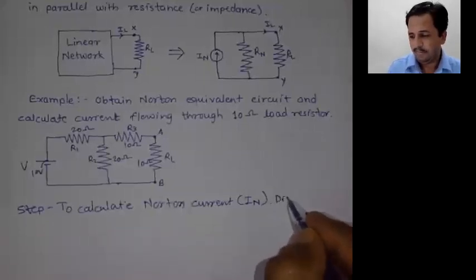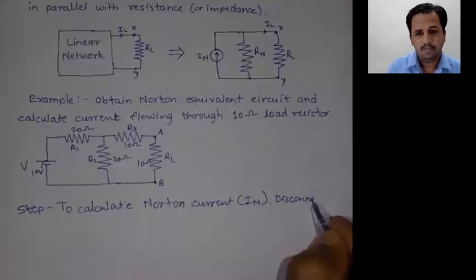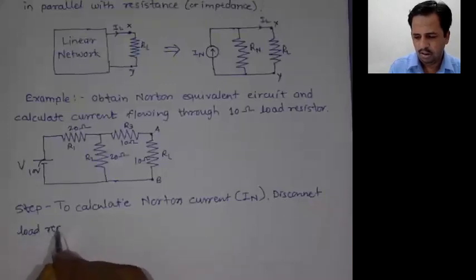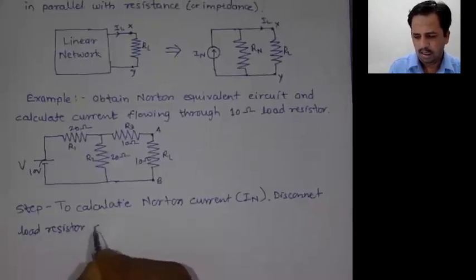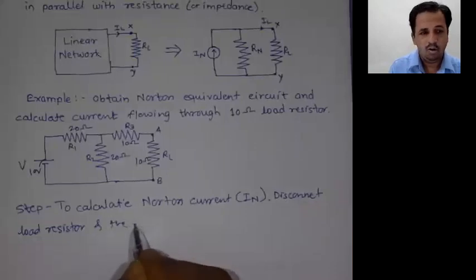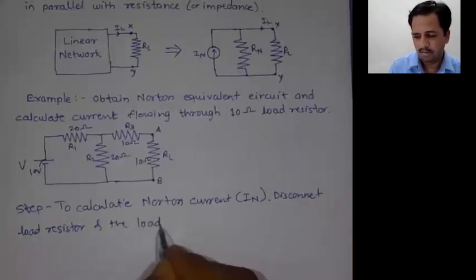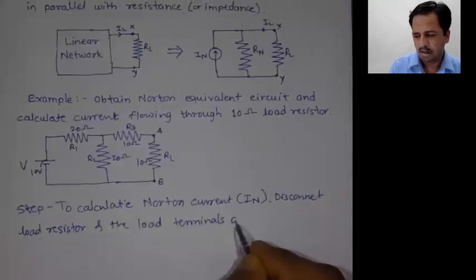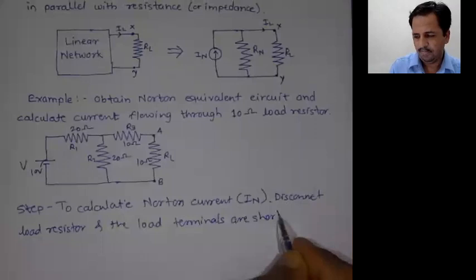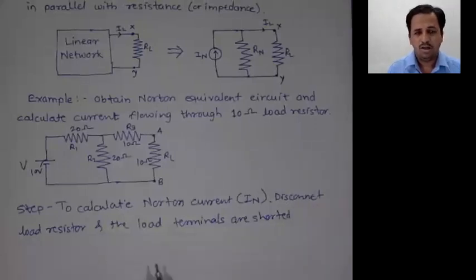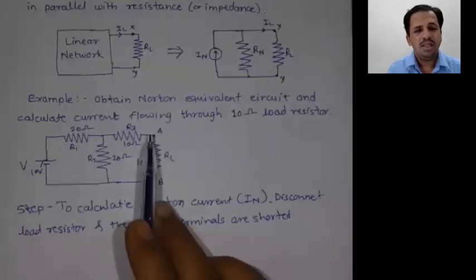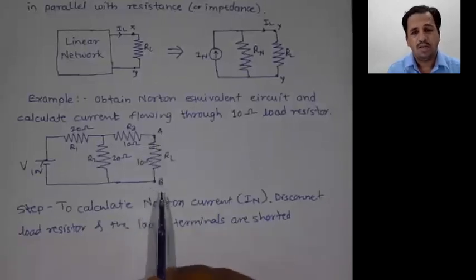Disconnect the load resistor, and the load terminals are shorted, or make them short. Means we have to disconnect this load resistor, and these terminals are made short circuit.